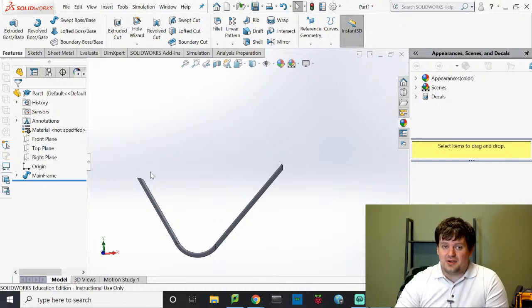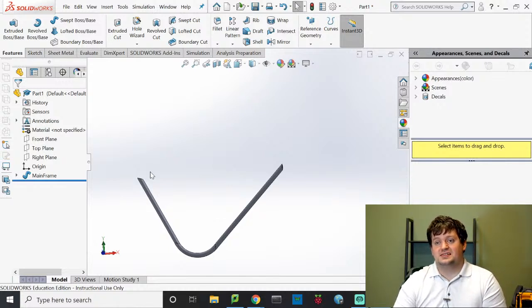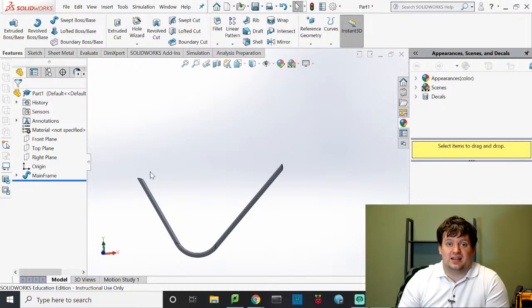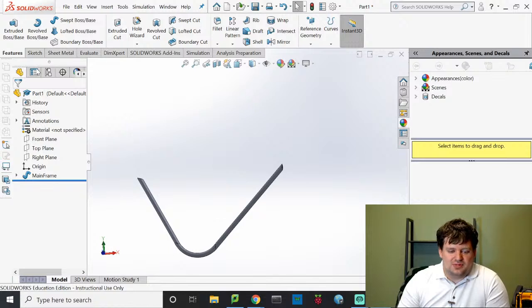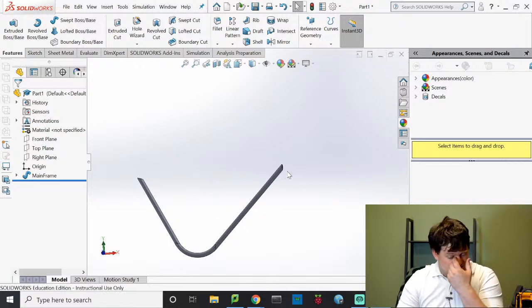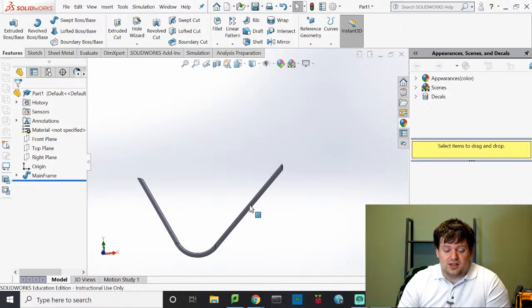And the nice thing about it is, if I make it automatically generate it for me, that is the type of component that would need to be generated in SolidWorks. So I'm going to show you that feature. This is not a feature that you'll probably use very often, but oh well. What I'm going to start with is I need to create some reference geometry. If I'm going to create a circle right here, I could create it on this plane, which is my right facing plane, but I want it to be over here in the center. So I'm going to create some reference geometry and I'm going to click plane.